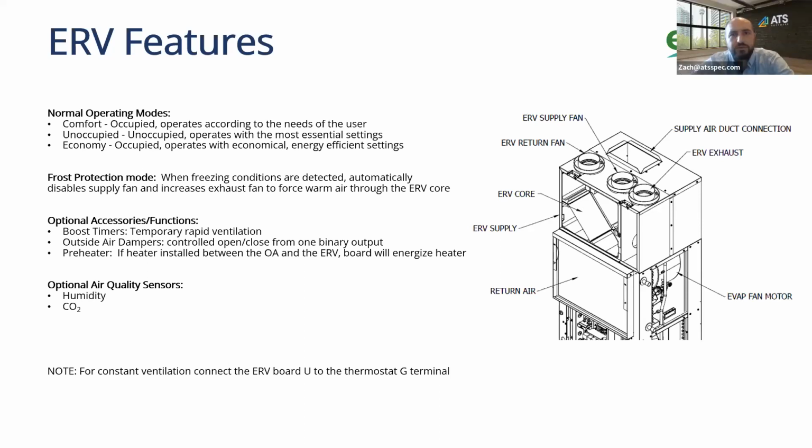I'm sorry. While we're on the subject of the fans, a question did come in for these ERV controls, asking whether or not there's humidity control, and is that tied to the fan? So if it's very humid or very dry, how does that affect the fans, or are they constant speed? Got it. Okay, so we have options for third-party humidistats and/or CO2 sensors that can be used to control the ERV. So it would take the call from that device and decide what needs to happen with the ERV.